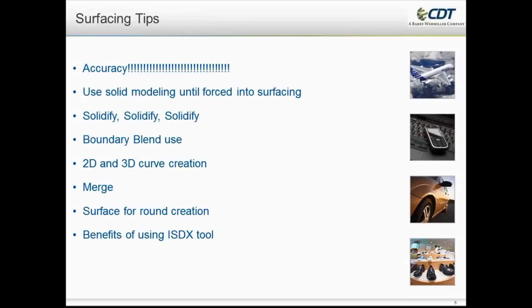There's very few times that you should be doing entire models out of surfacing work. If you break down your models, a lot of the time you will find that a lot of the things can be done in solids, extrude here or revolve here, and then the details and some of the surface curvatures will be done, and should be done, in surfacing. So it's something to keep in mind that when you are going through and doing surfacing work, as much as possible, try to make solid models, or at least solid portions of it, until you are forced into the surfacing realm.